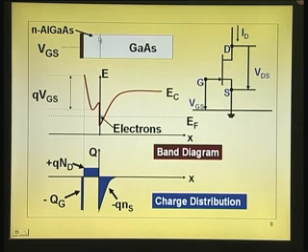I have not shown the spacer layer, it is understood that it is present there, it is a very thin layer. So, doped layer and undoped layer. Now, you can see the gallium arsenide layer is fully depleted, and VGS, I am not able to show it here because it is just through the gate layer the cross section is drawn. VGS is between the gate and the source.